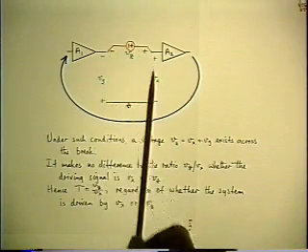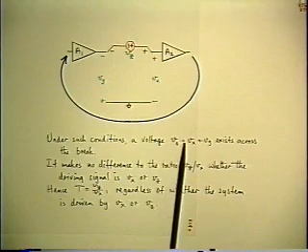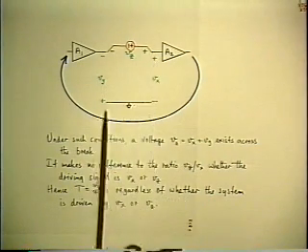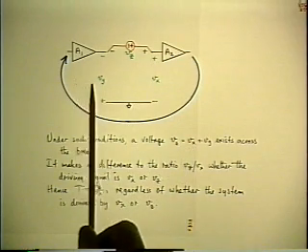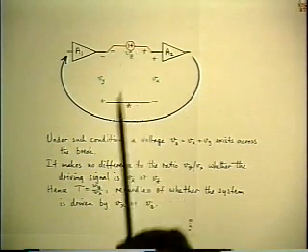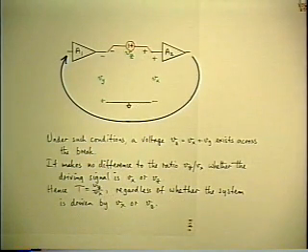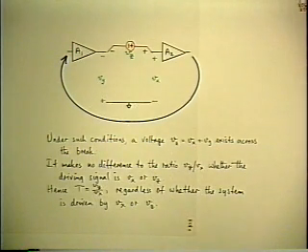And when you look at it a little more carefully, you see that the three voltages constitute a phasor triangle. Vz equals Vx plus Vy, which is one constraint on Vx and Vy. Because now the independent test signal is Vz, and you can set that generator to whatever level you like, as long as you stay within dynamic range. But both Vx and Vy are dependent quantities now that have to satisfy two conditions simultaneously.